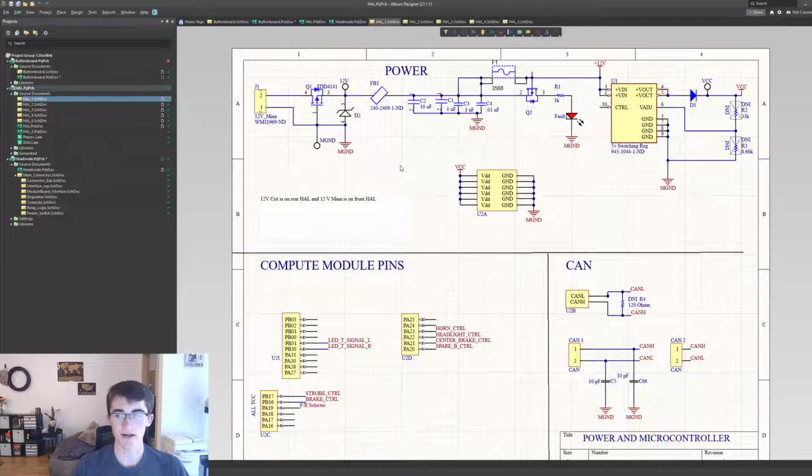Something like the turn signals where you have to turn right or left. There are front and rear turn signals on the solar car based on regulations. They have to be front facing and on the back of the car and on the sides based on certain angles of when you're viewing it, and they do test us on this at scrutineering.